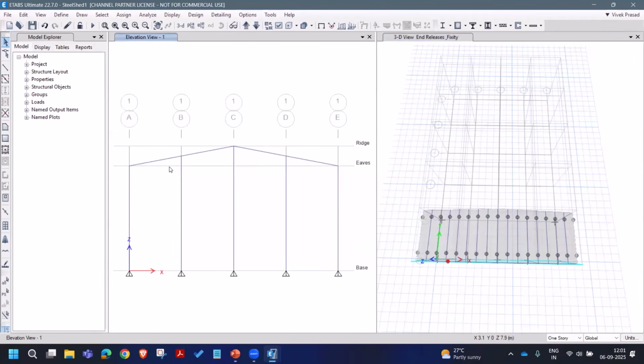modeling items, which should be the girt frames, which will be on the periphery of the building all around. So to create the girts, it will be a similar way, through the extrusion, but we need the joints along the height of these columns. So any one column is sufficient to start with. One option is to break this column and create, or the other option is to draw the joint objects directly with some offsets. So this would be useful when these heights are different.